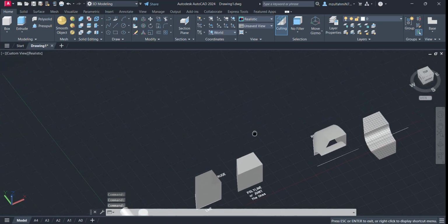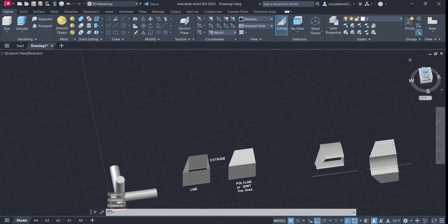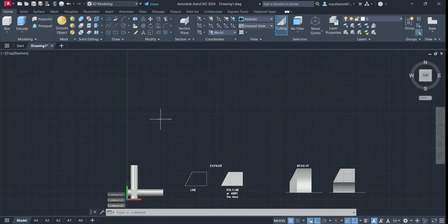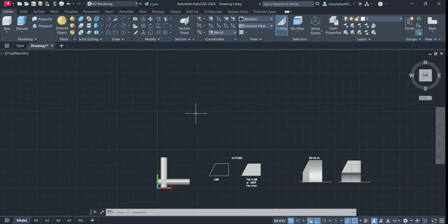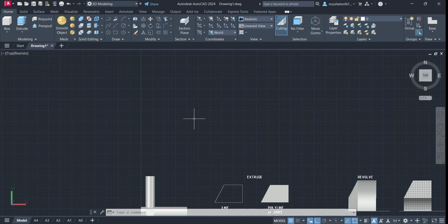So, okay, from the top view, or we try to create something like an aeroplane. Okay, so first of all, I want to create a wing first. Okay, we can click L, enter. This is the center line. For example, I click it here at 60 comma 115.